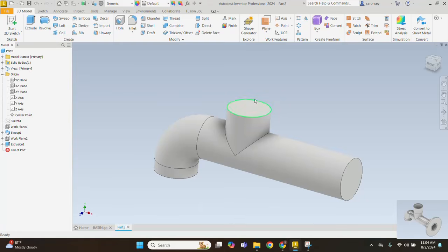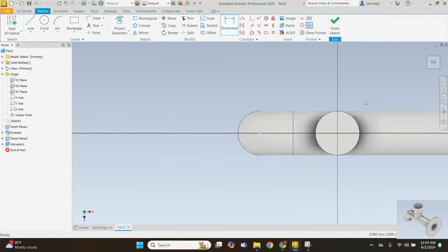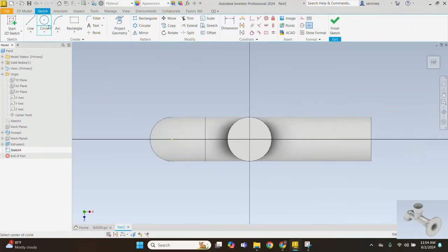There is another extrusion that sits on top of the surface. Let's create that. And so I'll select this face and create a sketch. Let me pick the circle command again. Let me draw a circle from this point. The diameter of this circle is 25. I would press enter. Let me also apply a constraint. So the horizontal constraint between the midpoints of that circle we just drew and the origin, and also dimension the distance from this point to the midpoint of that circle as 35.